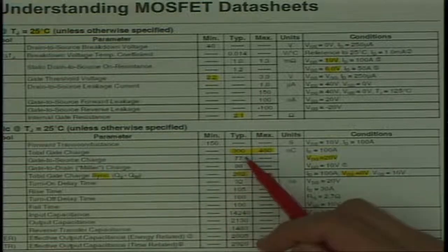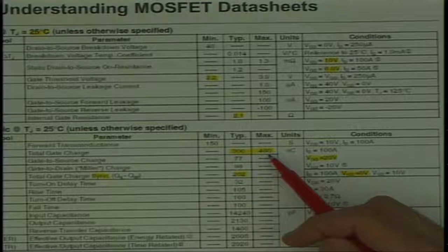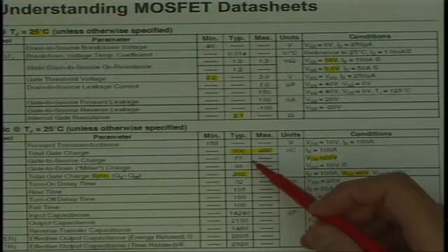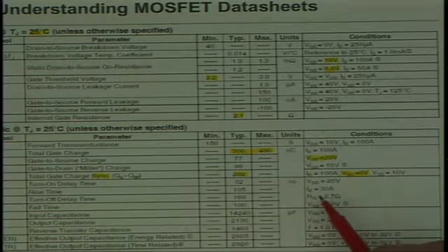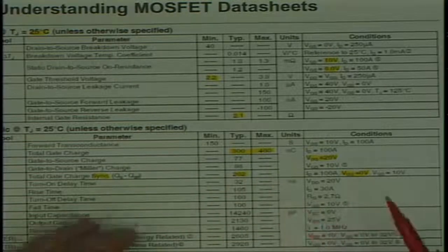We talk about gate charge. This is a measure. Remember, the gate looks like nonlinear capacitance. When you turn the FET on and off, all of that charge, all that energy is lost, right? You put it into the gate and you essentially dissipate it through another FET that turns the gate off. So basically, half CV squared F, this charge gets dissipated every cycle. So the larger the gate charge, the more inefficient your gate circuit is going to be. And there are different ways of looking at these charge numbers, and I'll talk about that a little bit more later as well.